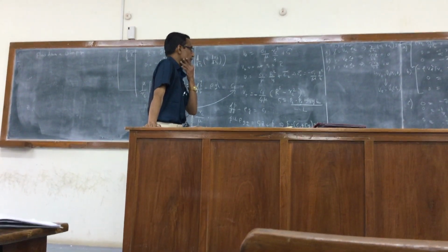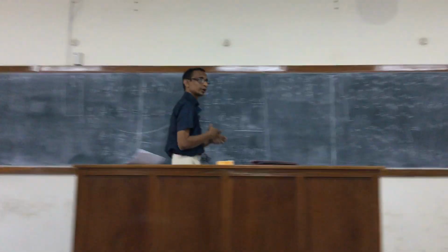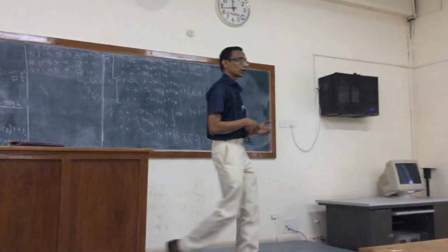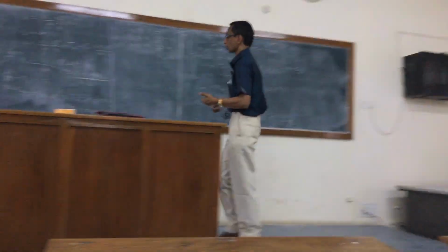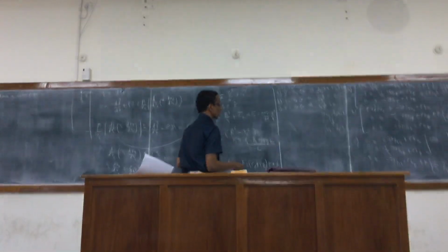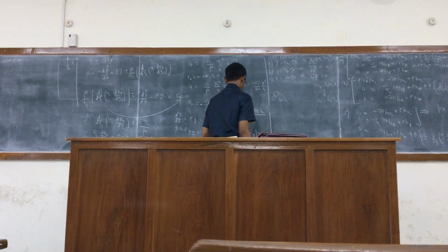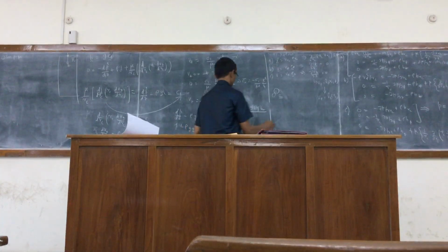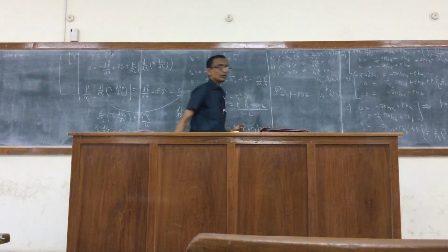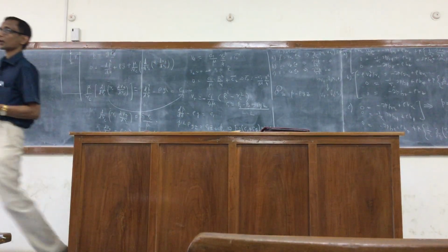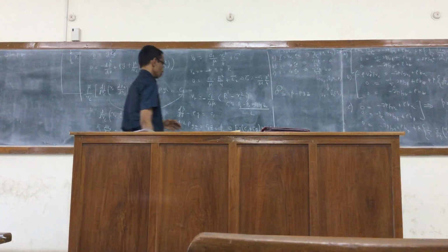So what is conventional is to introduce what is called a modified pressure, which takes into account the effect due to gravity. Right, so I can now introduce a new variable P, defined suitably as P minus rho g z. That's the modified pressure, right? P minus rho g z.